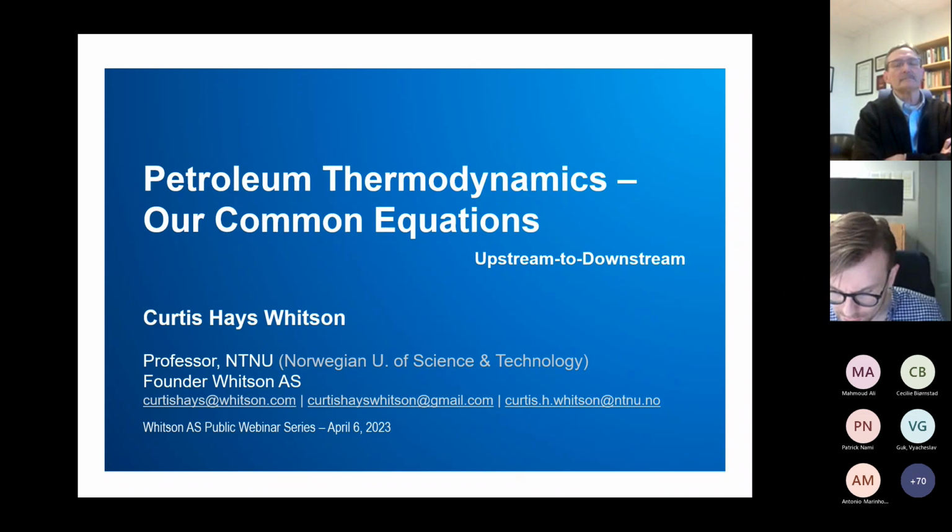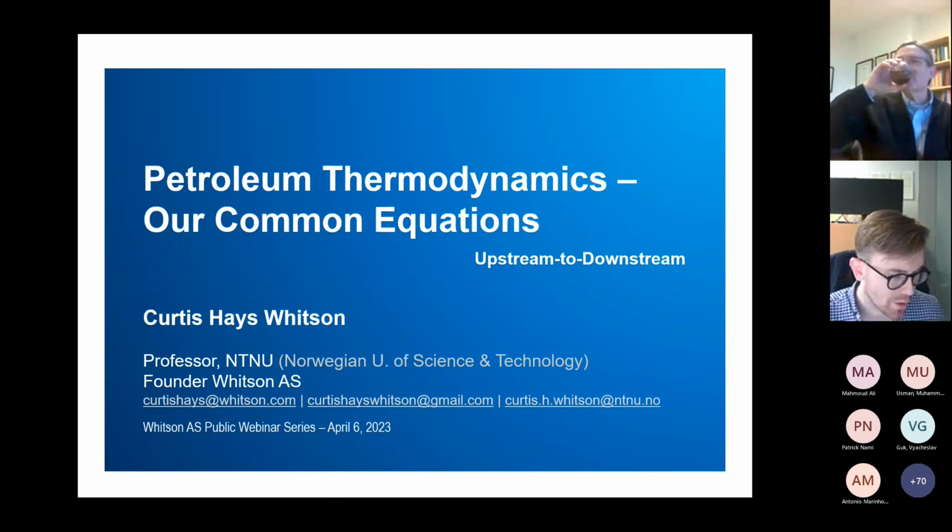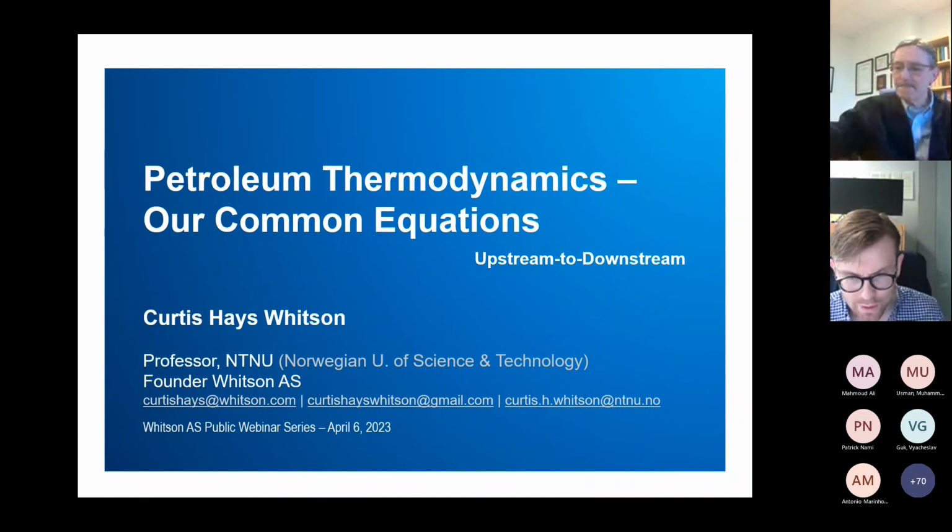Great. The other question, a common denominator of some of the questions, is related to pure components. You see in the last few years, like hydrogen, CO2, equations of state that are working very well for those type of systems as well. Are the equations of state that we've been using in the past, like Peng-Robinson, SRK, with just a few tweaks, good enough to model those systems, or do we have to do something special, especially, I guess, nitrogen, CO2, or methane, like pure single component systems?